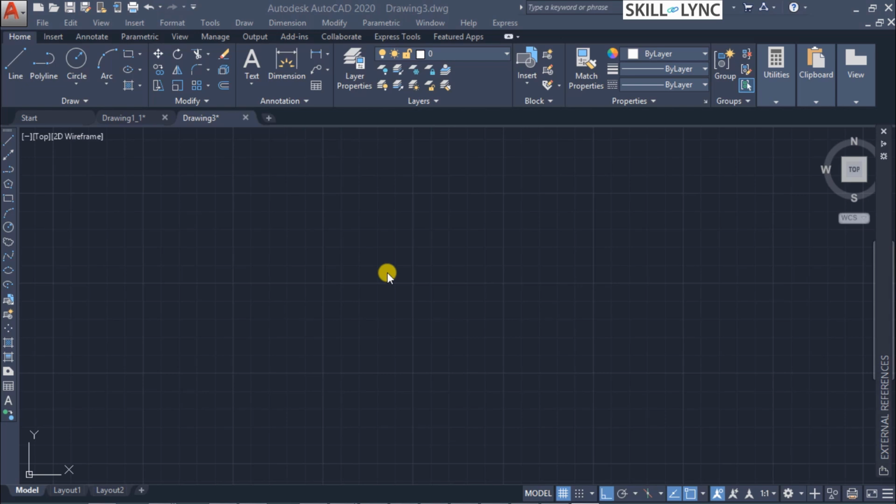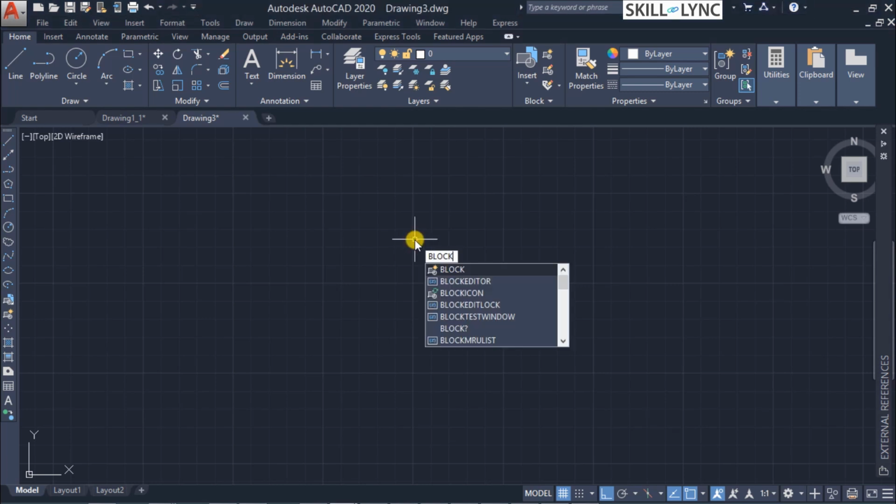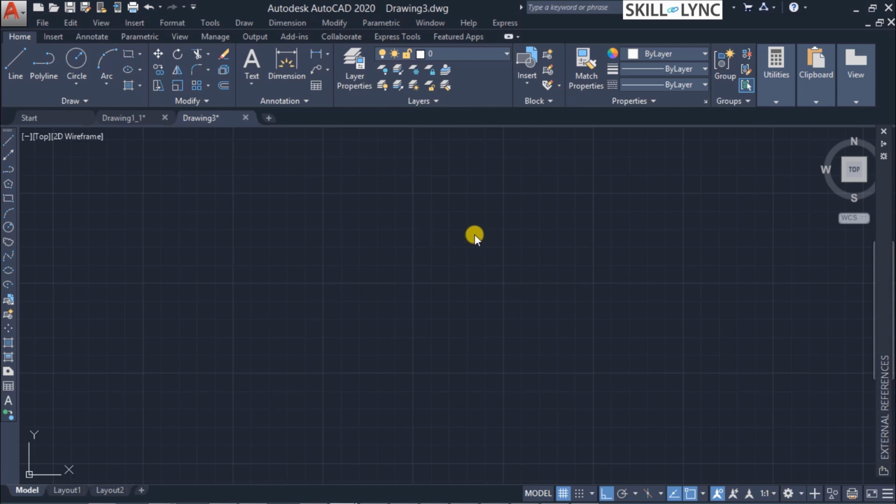Typically what you're doing is creating a link between the subassembly drawing and the assembly drawing through external references. This external reference is going to be a variation of the block. A block that we have done is a collection of geometry that is identified by a unique name and is stored in the symbol table, as we had seen earlier in the block. We'll quickly show. So when in the block, you can see that.